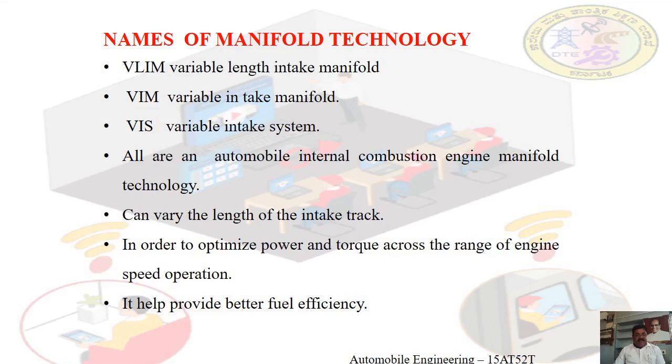In VLIM, VLIM stands for Variable Length Intake Manifold. The variable length intake manifold is a direct answer to the shortcoming of conventional tuned intake manifold. A fixed length of intake manifold is optimized for a very narrow revolution band.